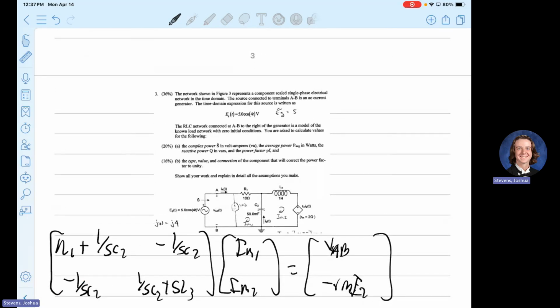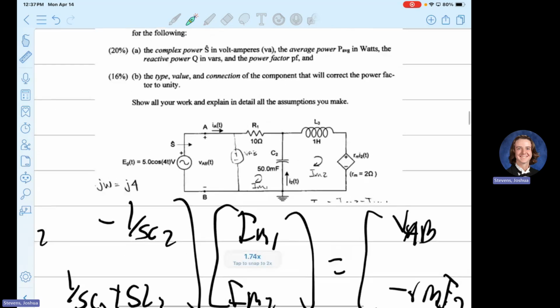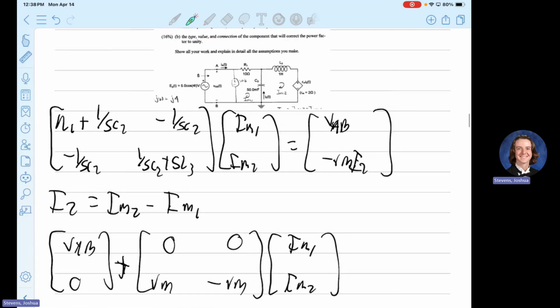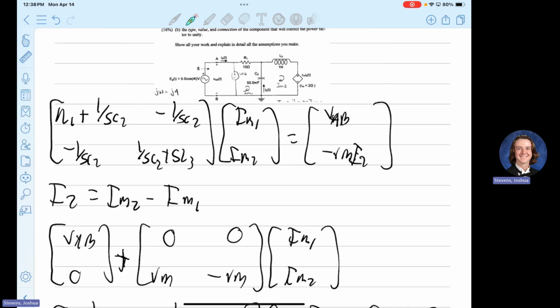So we want to find the complex power, okay? The input complex power, basically. And it's denoted as basically being right there. Well, what is there? There's a VAB, and there's what? Current. Okay. Well, what's an equation for complex power in terms of current and voltage? I agree, but what do you have to do to the I? Conjugate. Does everybody agree? Okay. So, I need to either find voltage or I need to find current.